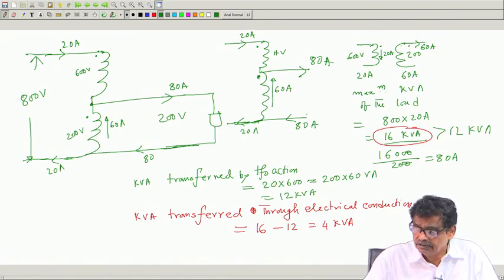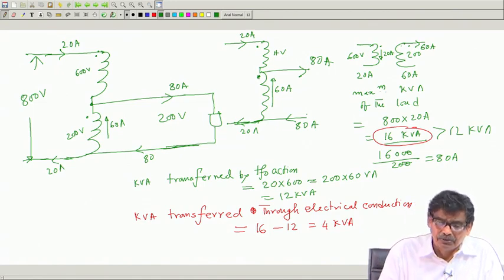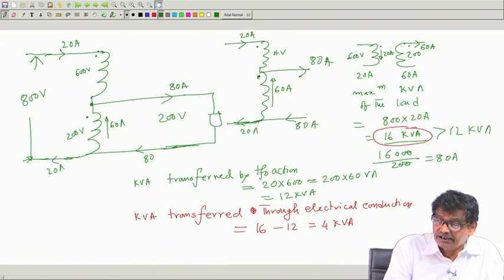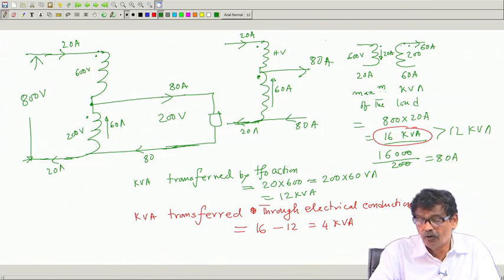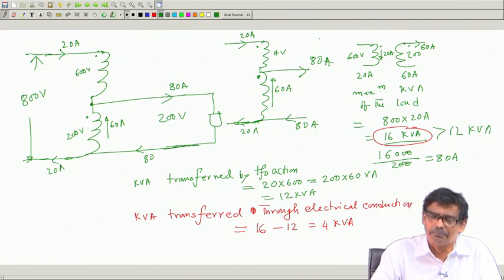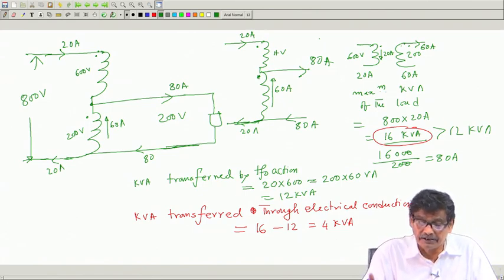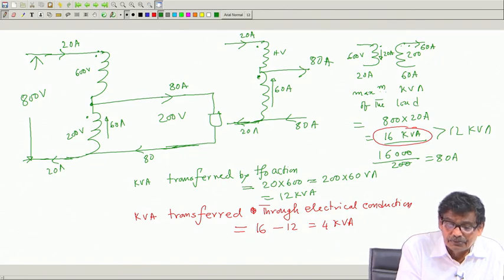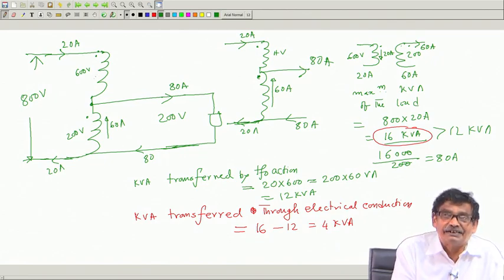You just think, and you can do that. Of course, these are the only two connections I have discussed. You try on your own how differently you can connect these two coils in series, applying appropriate voltage, mind you, to the windings, to get how much kVA, how much current. The interesting thing is, whichever winding is left out alone, you first fix up that current.